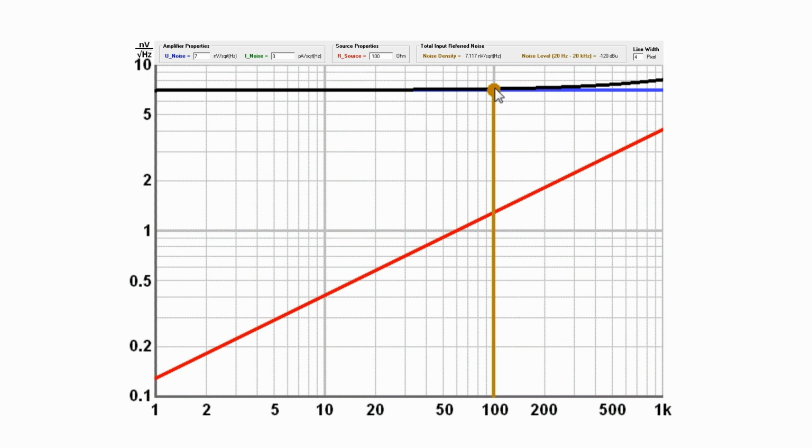If you would crank up the gain on your preamp so that you can hear the noise, you would mainly hear the preamp noise as expected. Even if you had a microphone with higher impedance, thus higher self-noise, let's say 400 ohms, the noise floor of the system would still be dominated by the noise performance of the preamp, because it produces considerably more noise than the mic itself. So far so good. I think this is all what we expected.